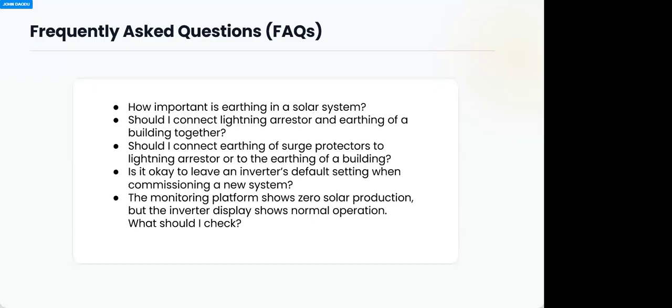Then the remaining flash that the roofing sheet attracts can go through anywhere and get itself into your solar system, still causing damage. So the cable that is coming from the roof must be thick enough. That's why you see in some places they use 25 mm, they use 35 mm, depending on how big. If you look at those earth tapes, they are thick. They can accommodate every current and drag it to the ground.